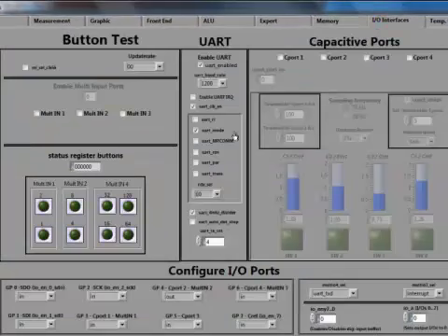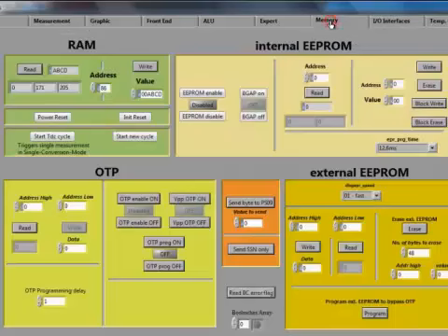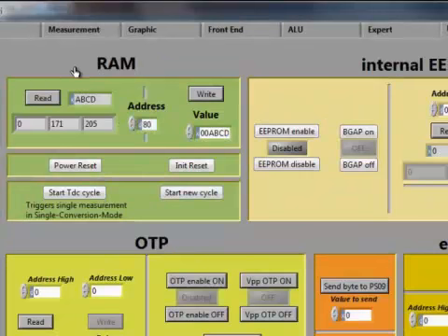Then select the UART trans option once and deselect it. This will generate the start transmission pulse and the 2 bytes are sent out in one go. You can recognize that the bytes have been transmitted by reading the UART register 80. Here you can see that bit 9 is set, that is, the transmit interrupt is set, which indicates the completion of transmission.